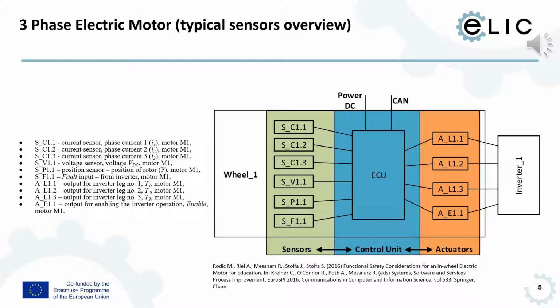So we have some mathematics and some diagnostics where we can see if the e-motor is perfectly controlled or not, because if the Kirchhoff law or the 3 phase currents are not 0 and it's not correctly coordinated, the 3 phase currents, then the motor will not run perfectly. So it would not produce the torque expected.